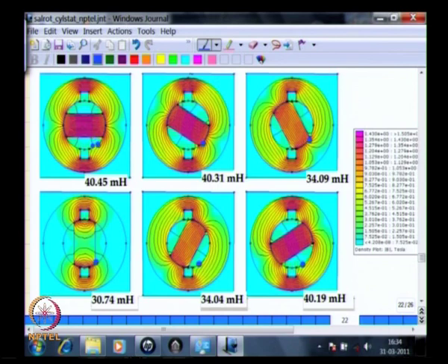So, as the rotor rotates, at any given angular location on the inner circumference of the stator, because the rotor is a salient pole rotor, the air gap is going to vary, and therefore even if we know the MMF at this place and we assume that the MMF variation around the circumference is going to be sinusoidal, we still do not know the air gap on which this MMF is going to act.